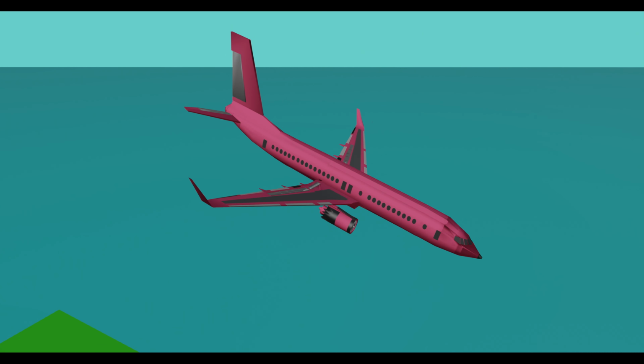It is good to note that when making a turn, it is professional to use both the yaw and roll movements at the same time. Therefore, rudder and ailerons are used at the same time to avoid a condition known as adverse yaw.